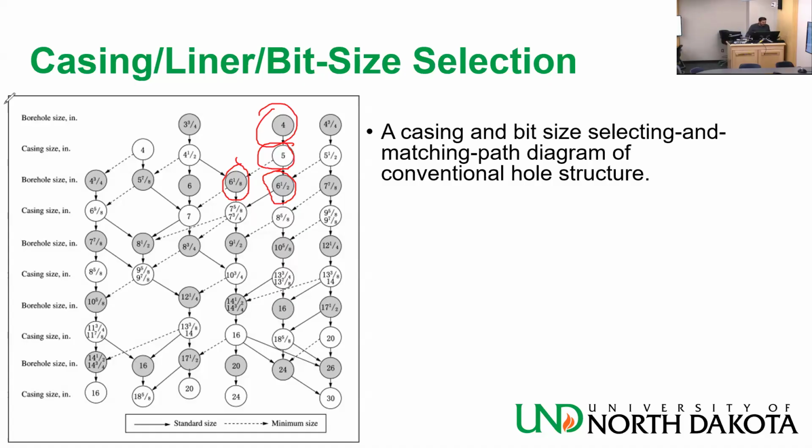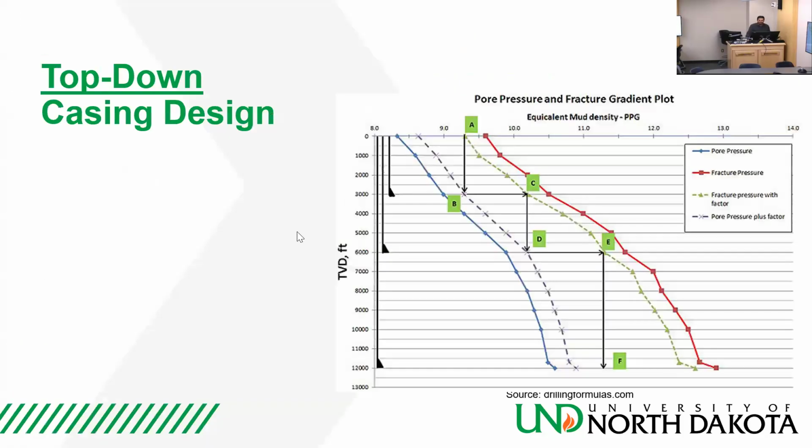So I need to basically make my planning properly. And I want to run as few casing strings as possible. If I can do it with 2 instead of 3, I prefer that, but of course I need to be safe. And we said last time I can do it with 2, but I need to get rid of the safety margin. The safety margin is important because I really don't know how accurate my mud window is. Somebody gave it to me, and that doesn't mean that he has data from every depth. Somebody designed it for me. It's not necessarily correct, but I hope it's good enough.